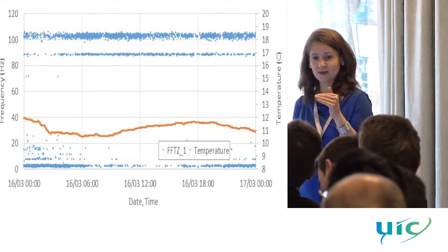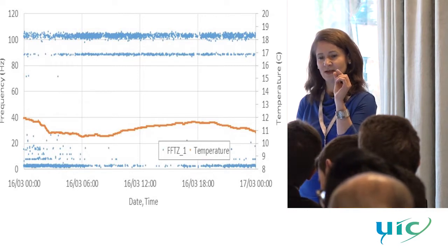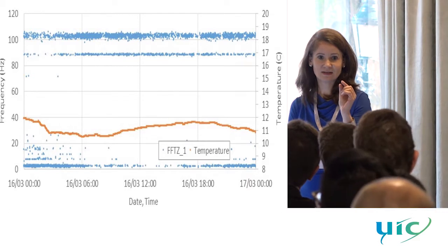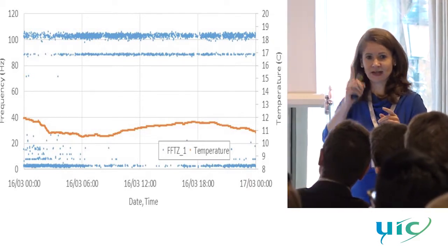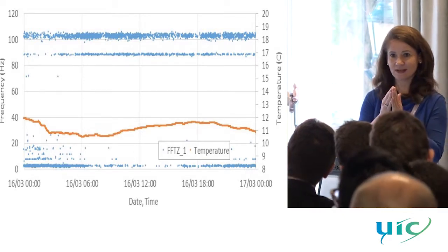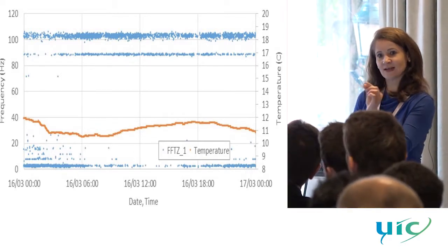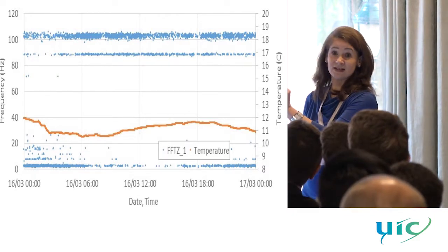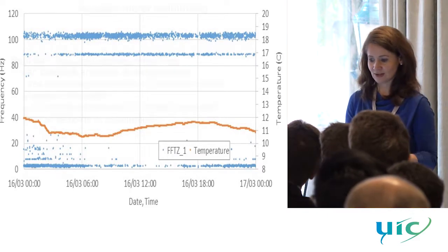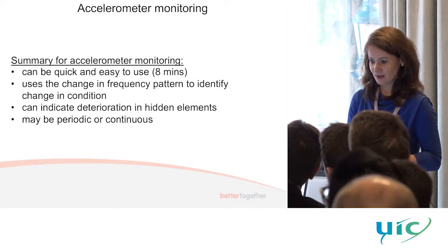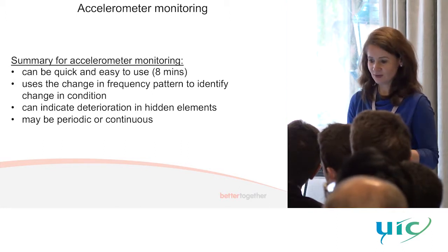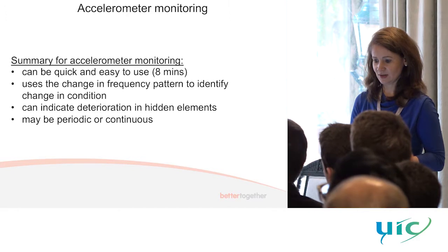And the only reason we can do it is that we analyze the signals every 8 seconds. If you did it for an hour, you'd only get 1 dot, where the natural frequency with and without traffic would be mixed. But there are certainly 8-second intervals where there isn't very much traffic, so you can pick up the traffic noise and the dead noise as well. So the ideal period for monitoring is 8 minutes, but 1 minute is also sufficient.